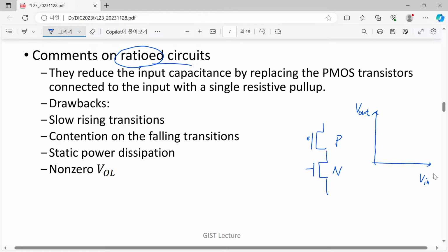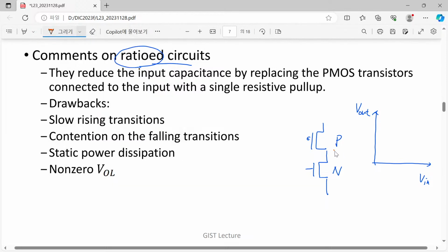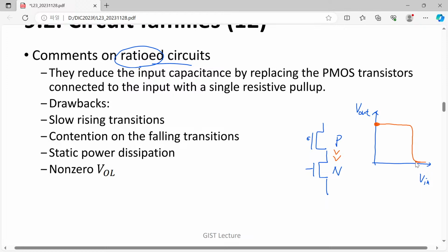If we introduce once again this voltage transfer curve, everybody understand if we have a much wider P MOSFET, then since pull up network is much more powerful than that one, we will have this kind of behavior, highly skewed to the high value. And also if we have the opposite case, if N MOSFET is much wider than P MOSFET, then we will have this behavior.